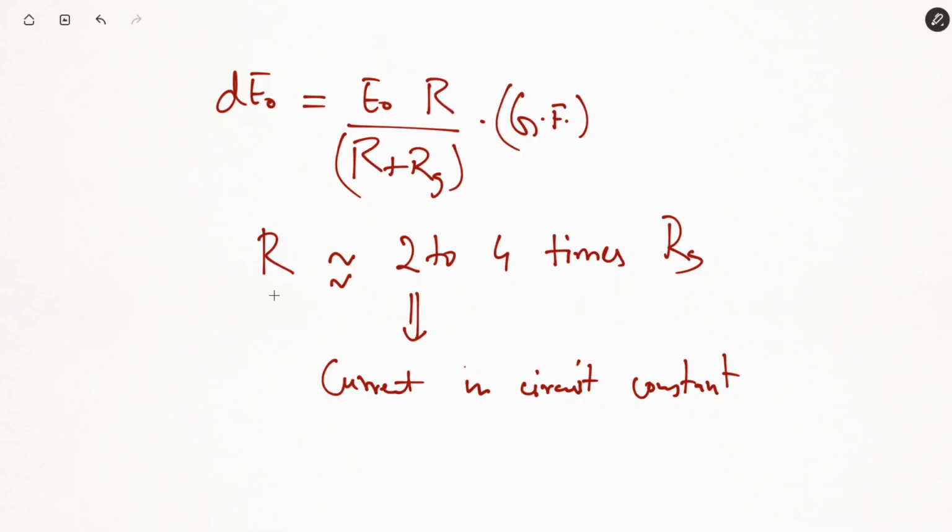We can also measure resistance of the strain gauge using a Wheatstone bridge principle. So you already know in case of a bridge circuit the equation is simple, and the opposite resistances balance out each other, and accordingly the device can be set for calibration. So without going into further detail, we'll wrap up the resistance strain gauge here. We'll do some numericals on the resistance strain gauge in the next session.